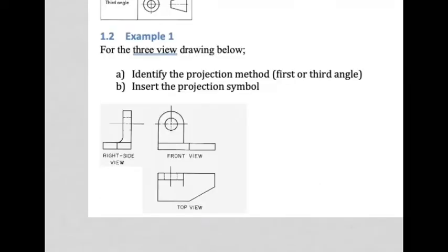So with that in mind, if we were to draw this object from one of the sides, be it from the right hand side or the left hand side, only from one of those would we see the hard line I spoke about just now. And you can see it over here, there's that hard line. So it stands to reason that this view is in fact in agreement with what they've said here, that is the right side view.